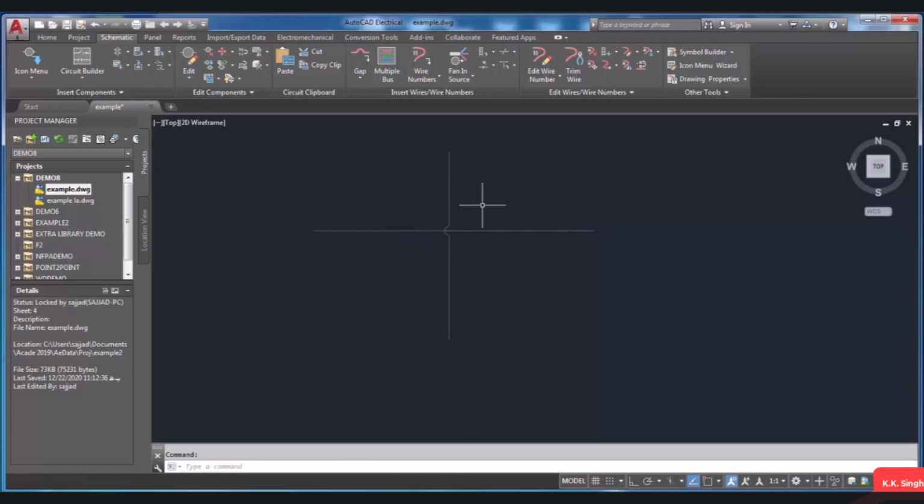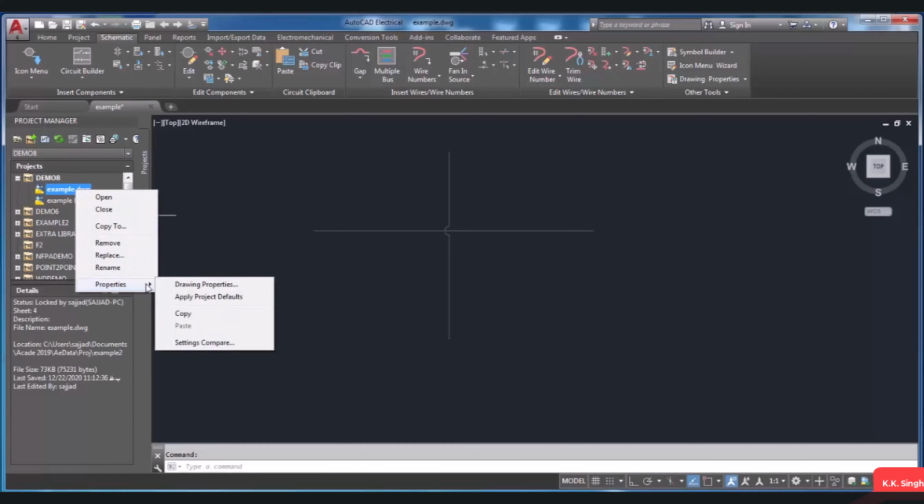As the wire gaps can be created, you can also remove them. In order to do that, go through the previous steps again. I mean that you need to change the gap to solid. To do so, go to your drawing, right click on it, choose Properties, then Drawing.